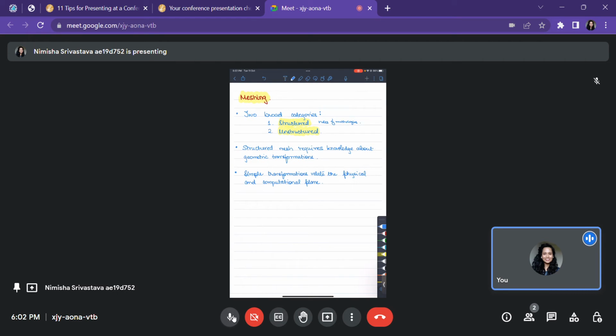So basically, structured mesh was really popular earlier, and also for research applications. Many times, a structured mesh is preferred because it gives more flexibility with respect to the way that you want your mesh to look. That is, it gives you more flexibility when you want certain areas to be more dense or certain areas to be more sparse as compared to unstructured.